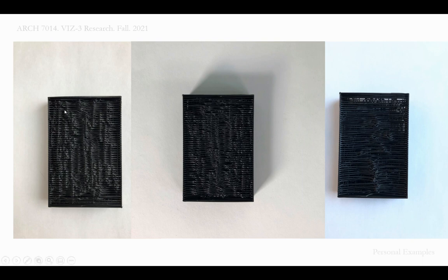You can take that F function and bring the speed way down, but leave the extrusion the same, and it'll keep extruding a lot of material at a time. And that's how this wavy pattern takes form: I began with a lot of material that I just pumped into the box to fill it up.